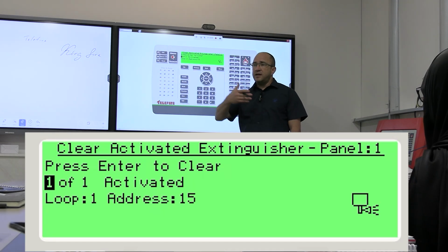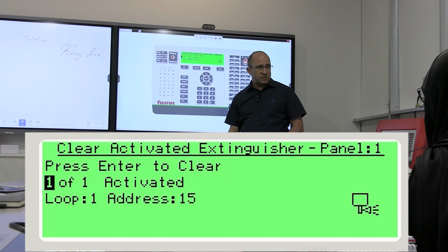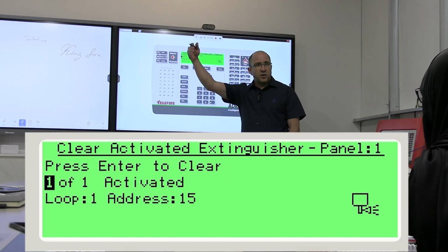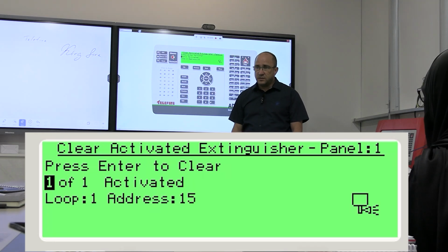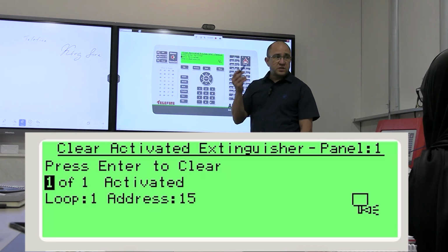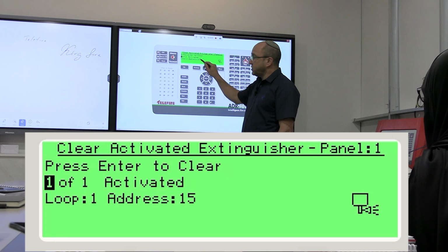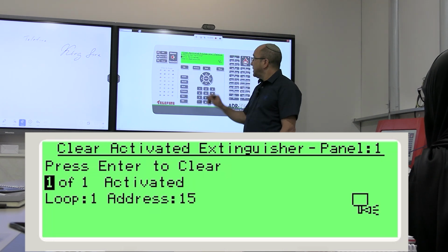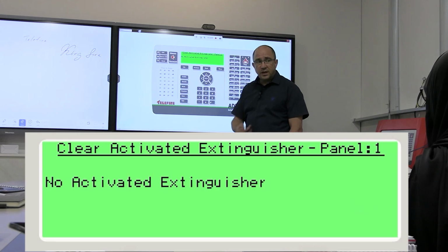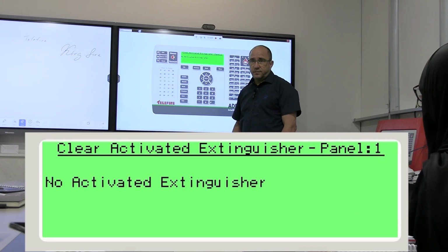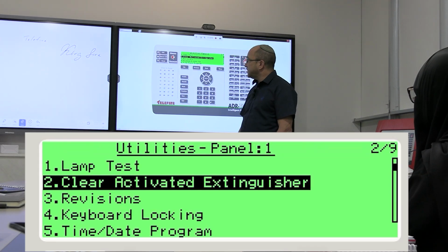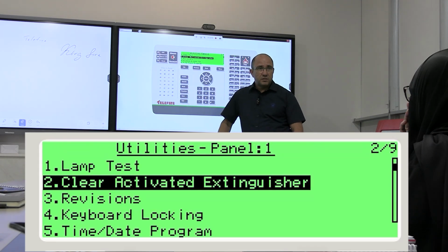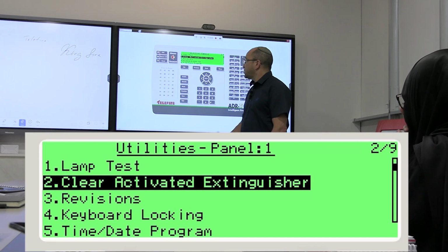Maybe I have 20 extinguishers that were activated during a long period of time because they didn't do anything about it. So I will choose the relevant one, address number 15. Press enter to clear. Click. Cleared. Fix. Perfect. Revisions.